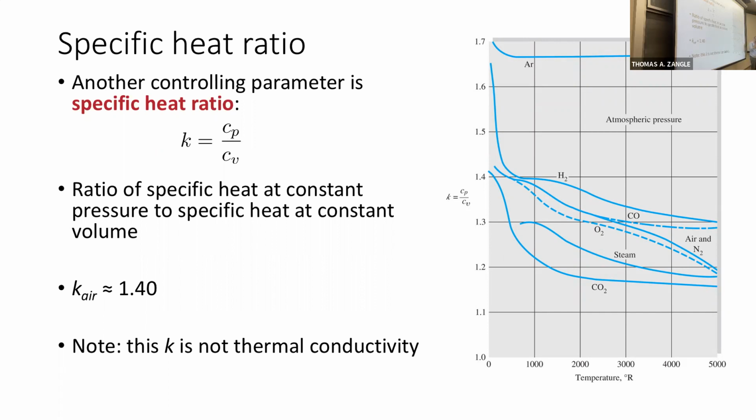Okay. But if you're considering compressible flow or compressibility effects inside of a pipe or a fitting, we'll talk about that, then this is generally going to be a pretty good assumption. Those shock waves are not going to be crazy strong. Yeah. So if you're getting to hypersonics, this is maybe not such a good assumption, but for transonic, supersonic, up to that kind of range, this is generally going to be pretty good. Okay. Other questions? Good question.